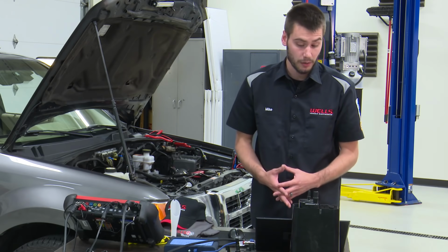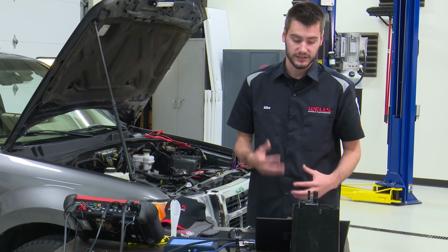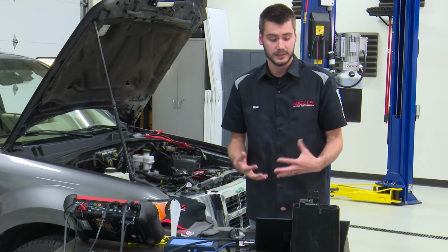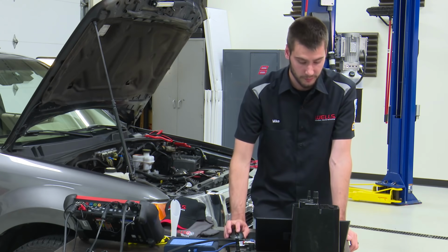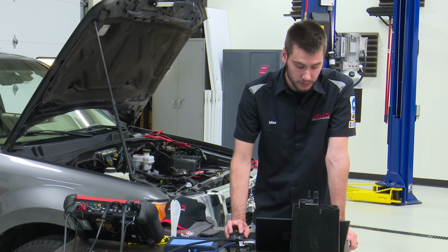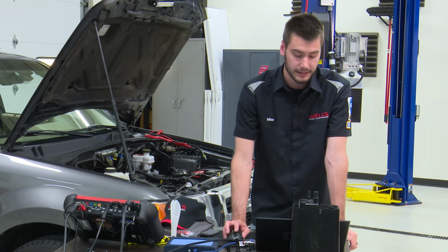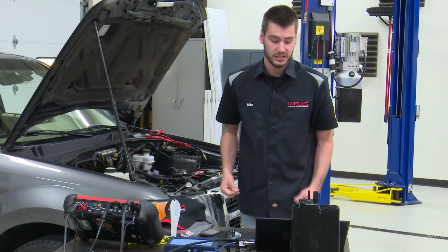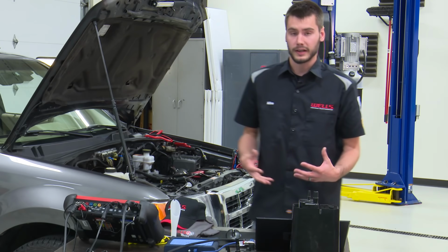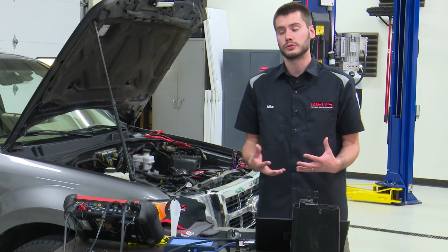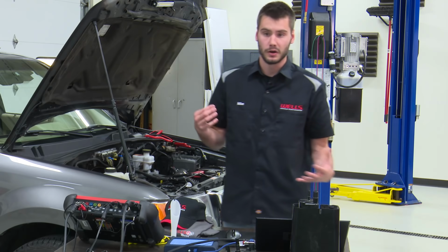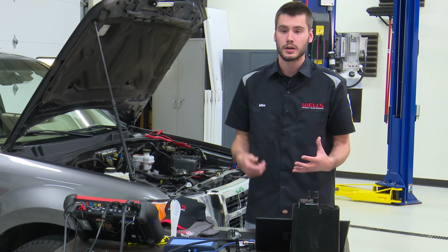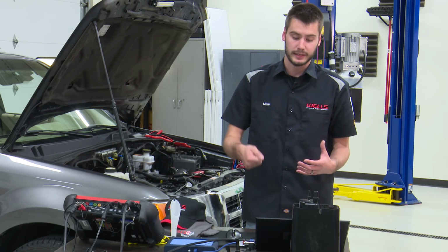Now, there are some conditions of sticking open purge or vent solenoid, something like that, that could cause drivability concerns. So this unable or hard to refuel, the fuel pump keeps clicking off, and that's the nozzle at the station keeps clicking off. Well, like I said, you have to have some way to displace all those vapors and air that's inside the tank when you're filling, otherwise the nozzle's going to keep clicking off.